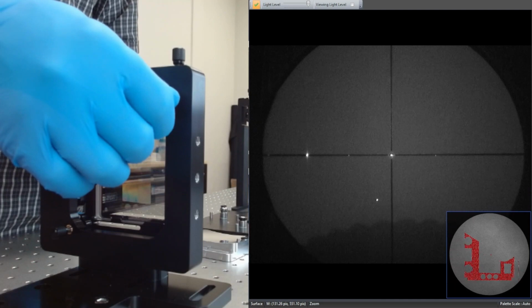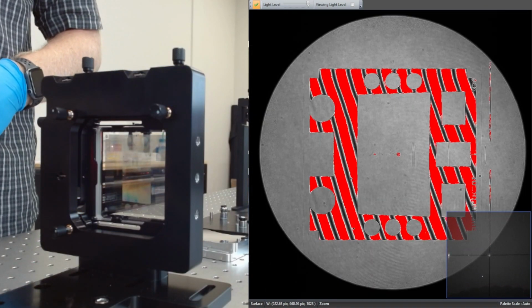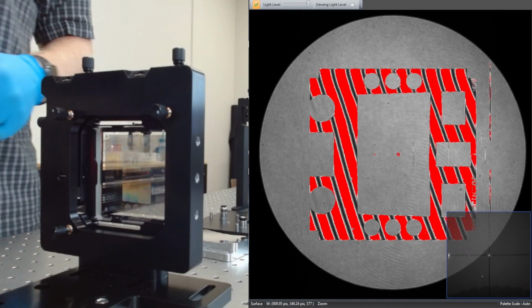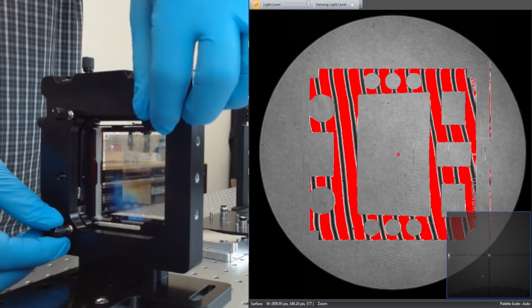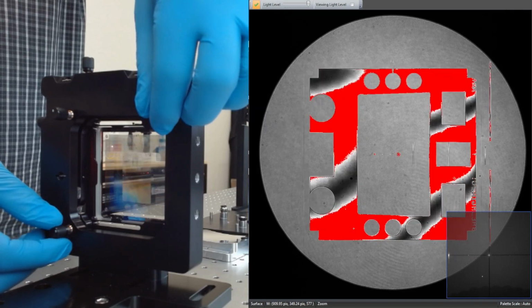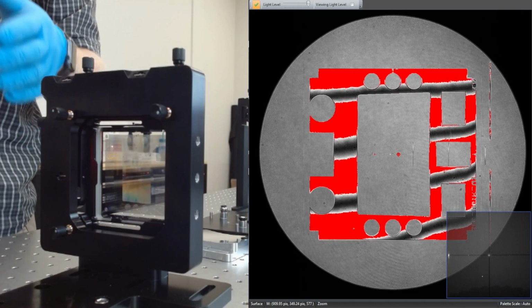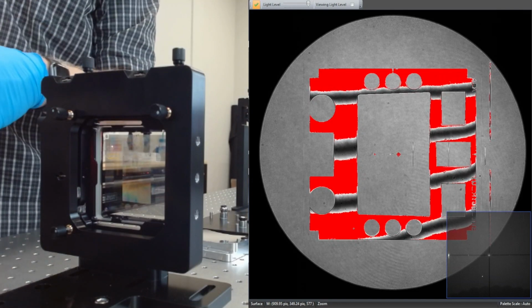Now, when you switch to view mode, fringes should be present in the retro alignment pattern only. Fine align the retro fringes with the FP3 stage. And the CGH is now aligned to the interferometer and will require no further adjustment.